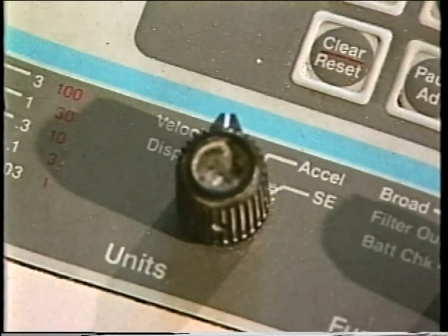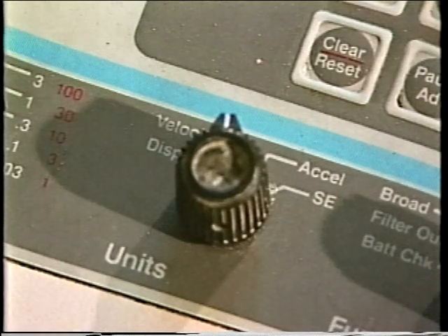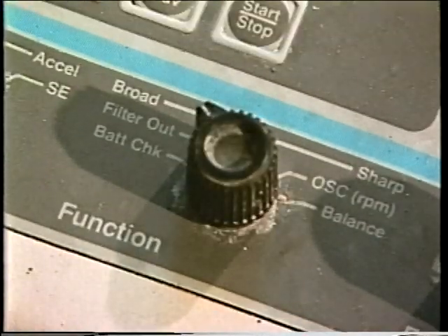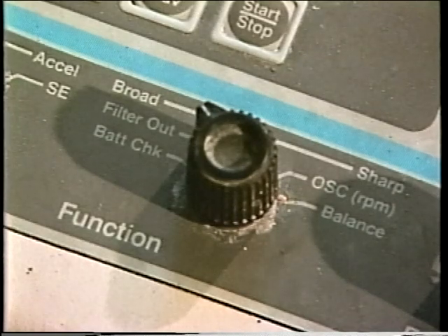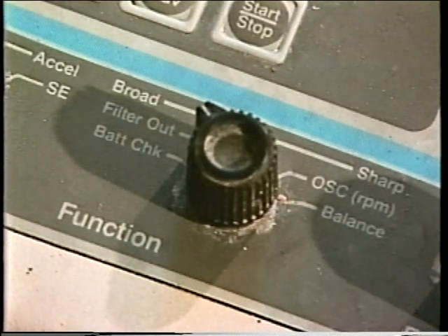Usually, velocity is checked first, since it provides an accurate reading of vibration levels over a wide band of frequencies. Once the parameter has been chosen, the frequency band is selected. Here again, it's a good idea to start by measuring the overall vibration level, which is the vibration that's occurring at all frequencies. That gives a good overall picture from which specific frequencies can be chosen and examined if necessary.